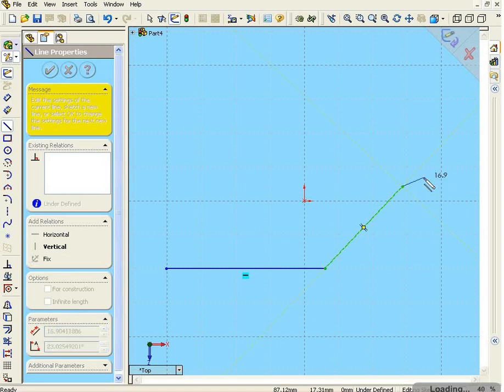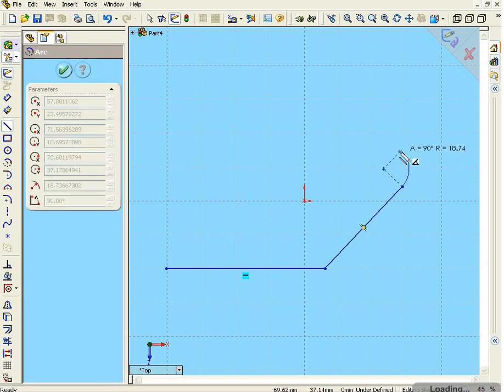Now let's create a tangent arc. In order to activate the Arc tool, drag the pencil tool over the last point. Now the Line tool becomes the Arc tool. You'll see a blue dashed line following the Line tool. This line represents the actual geometric relationship. In order to change the direction of your arc, move the arc through the point of origin again.